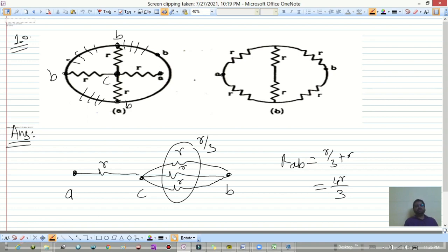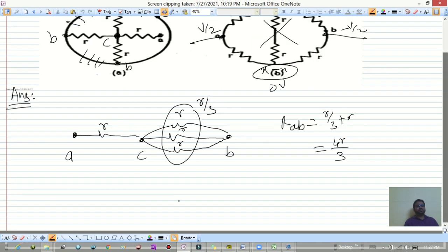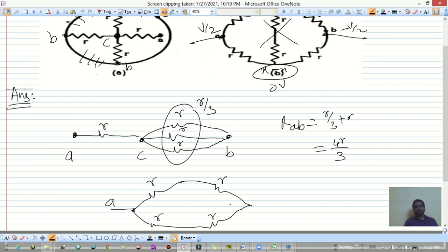Chalo. Now between this A and this B, we want what is called as the equivalent resistance. So same thing, in this V by 2, minus V by 2. V by 2 in this R, if it is X, minus X. In this R, if it is X, this is minus X. Indicate this is 0 volt. This is 0 volt. No need to draw this. So the circuit will become very simple, and we will have this is R, this is R, this is R, this is R, this is A point, this is B point. Right now, this is for A, this is for B solution, right?